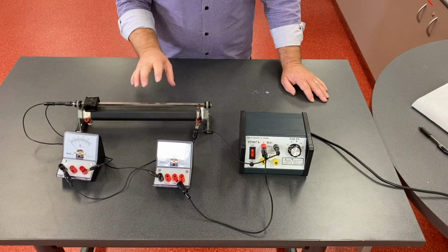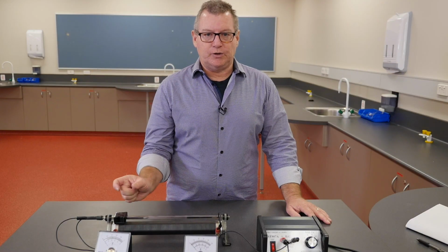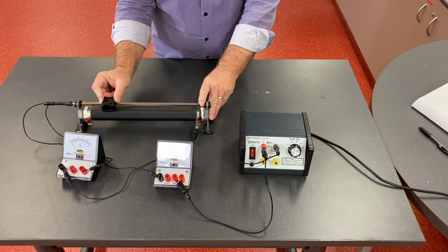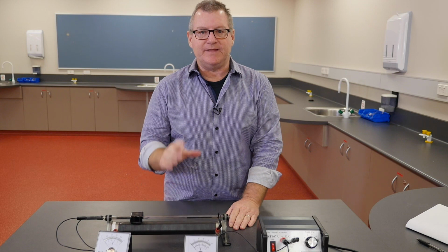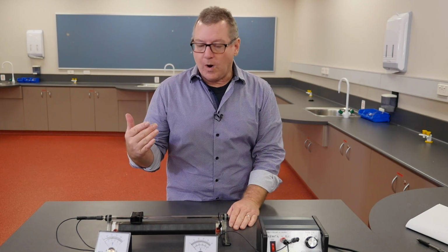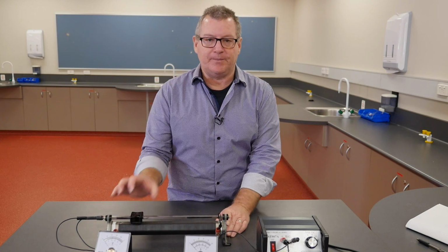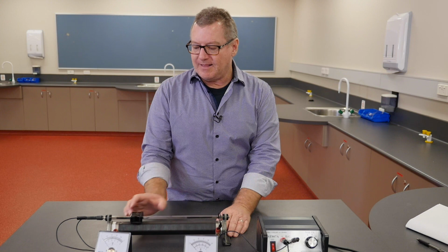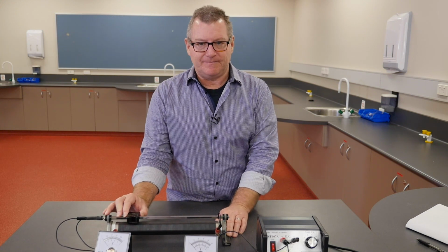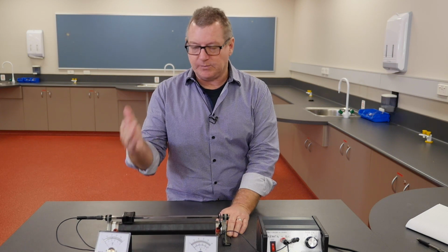This is a rheostat. It's a very old school style of variable resistance. You can slide the slider along to change the number of coils of wire that you include, and therefore the length of the wire and the amount of resistance. What we're going to do is keep it constant and calculate what value we've got it set on, because it's a very good tool, but there's no calibration. I can't say, all right, I'm going to set it on 50 ohms. I can basically just say this is where I'm going to set it.